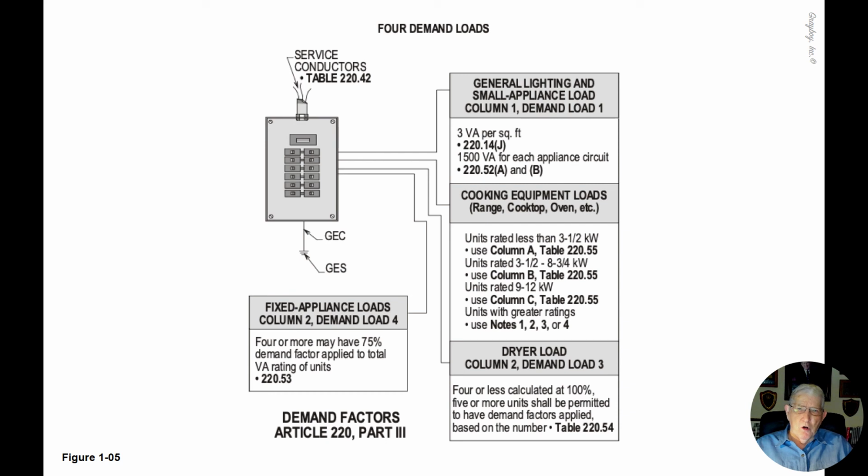Now, one thing, be sure you understand that the code only lists demand factors less than 1. If diversity is brought up, your answer for diversity factors is more than 1. For example, 100%, if you have a demand factor, it would be like 90%, 80%, 75%. But for diversity factors, you're greater than 100%, like 1.5, 2.5, and so forth. Now, you would have to obtain diversity factors from the McGraw-Hill Electrical Engineering Handbook or a compatible electrical engineering handbook. So the code, I haven't seen any diversity questions.